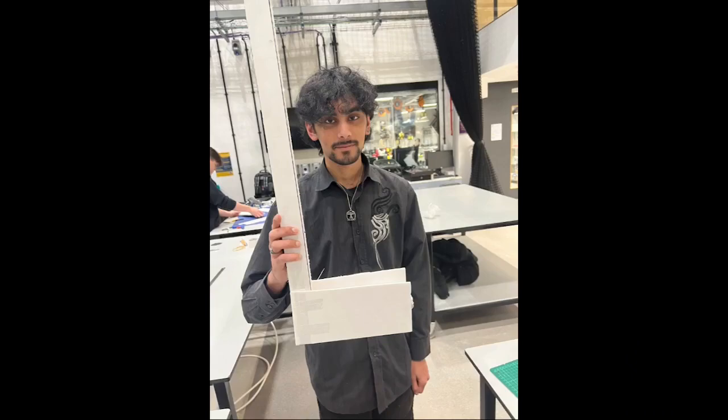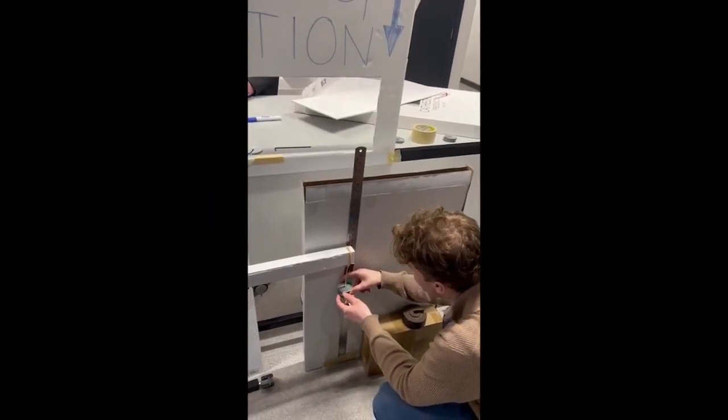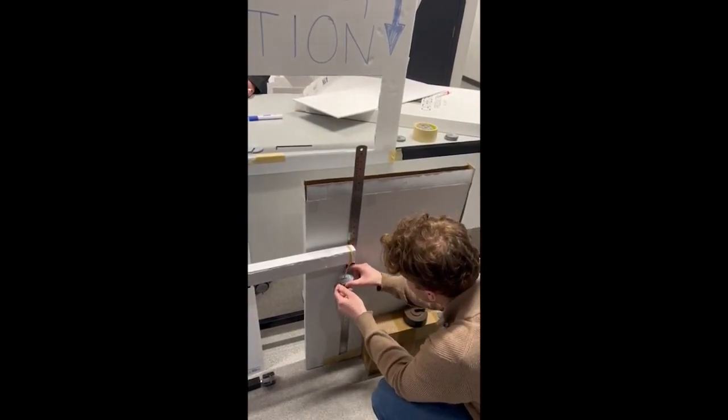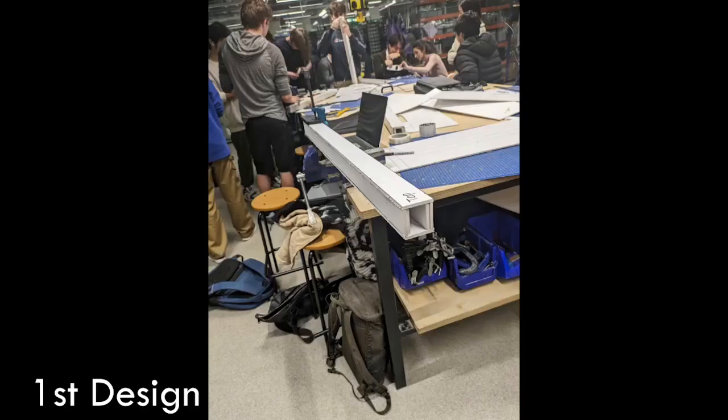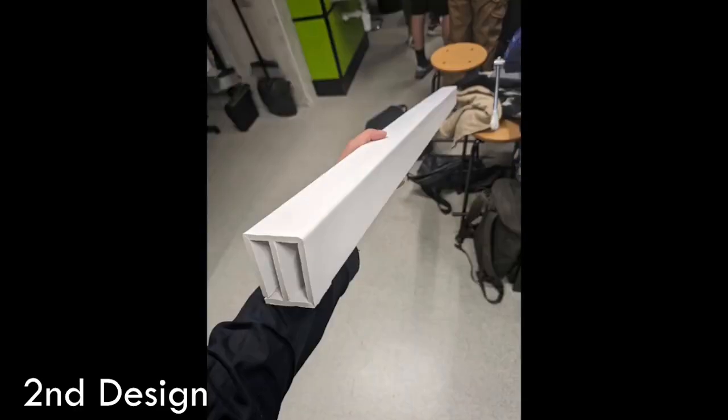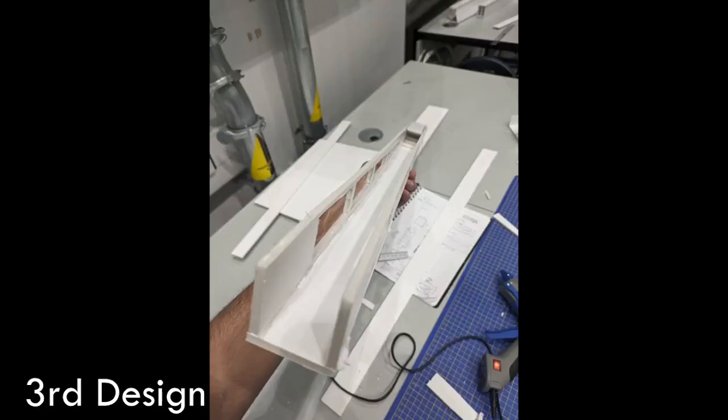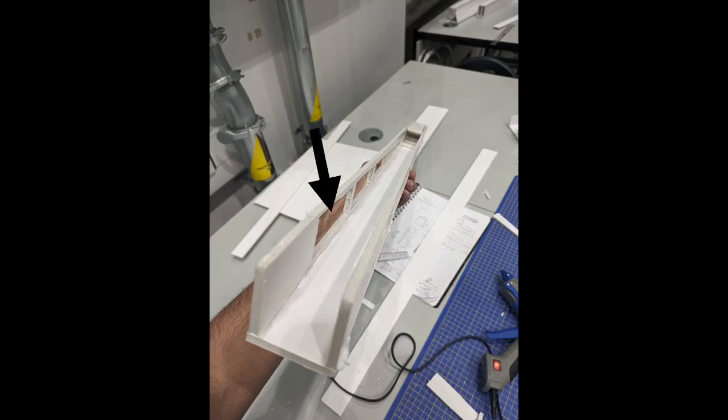This made our group quickly realize that a good spar design required a lot of preparation and testing before being manufactured. Going from our first design to our second and third was a big change, as we would take into account the requirements of spar geometry as well as bending and torsion tests that we would conduct in the lab. Making these changes, however, increased the weight of the spar, so in order to compensate for this, our group finalized our design by using laser cutting to skeletonize the spar in areas that were not experiencing stress.